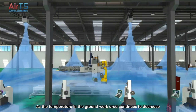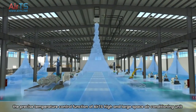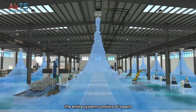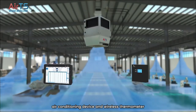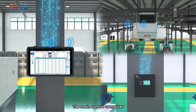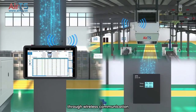As the temperature in the ground work area continues to decrease, the precise temperature control function of AirTS high and large space air conditioning unit monitoring system starts working. The entire system consists of three parts: the main control computer and software system, air conditioning device, and wireless thermometer. The wireless thermometer can be placed anywhere with a 220V power supply. The main control computer automatically inspects the wireless thermometer data and device operation data through wireless communication.